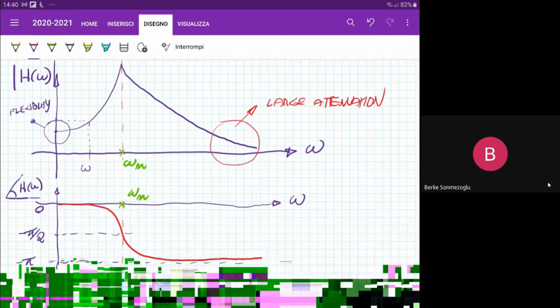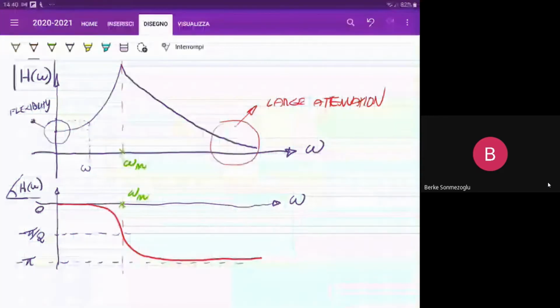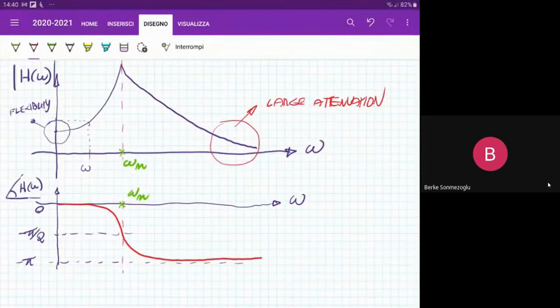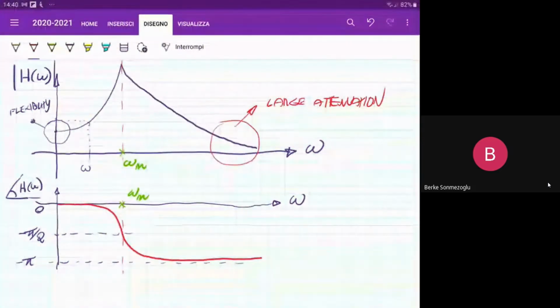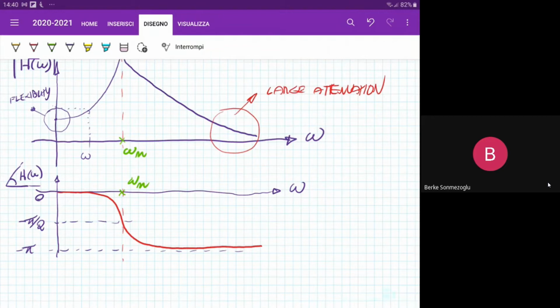And that means that there is an out of phase response with respect to the input when omega is getting very high, going to infinity. And here we are in the opposition condition. That is, the phase angle is pi, and therefore it is characterized mainly by a change of sign when you are considering an input excitation with very high frequency with respect to the natural frequency.